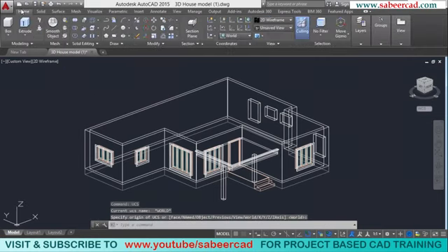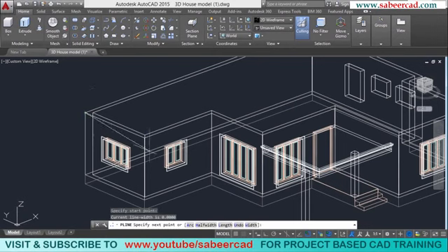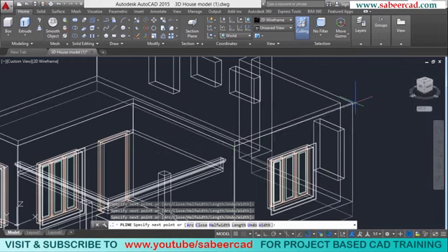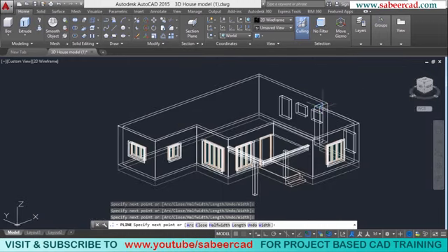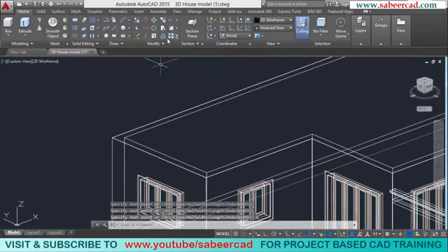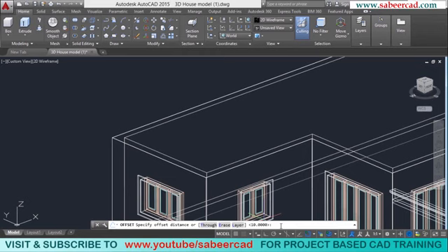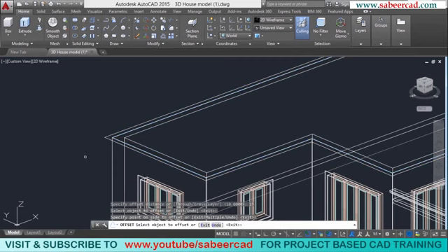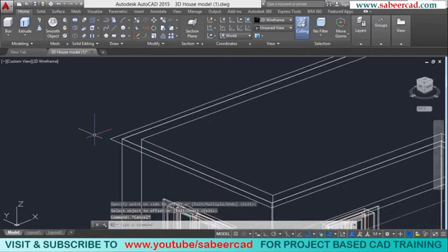When you give an enter, it will go back to the world coordinate setup. Next, I'll use polyline command and I'll sketch the boundary. So I'll pick the various corner points in the top of the roof. Then I'll close to complete the polyline. Next, I'll go to offset command and I'll offset this polyline through a distance of 15 centimeter. So I'll give 15 and this is the object offset, which is the polyline, and I'll pick a point outward. Now it is offsetted outward.